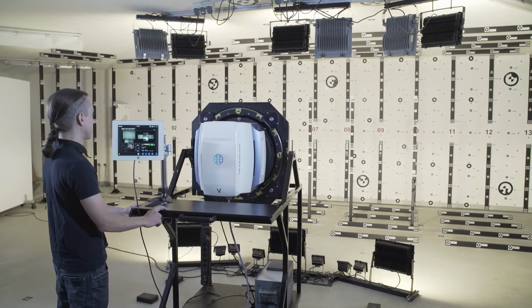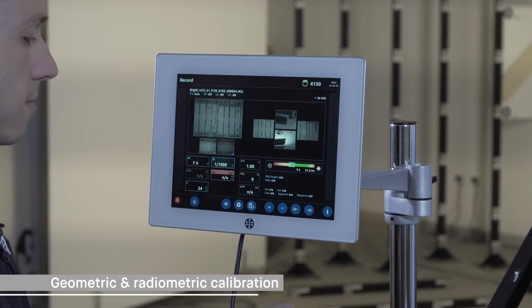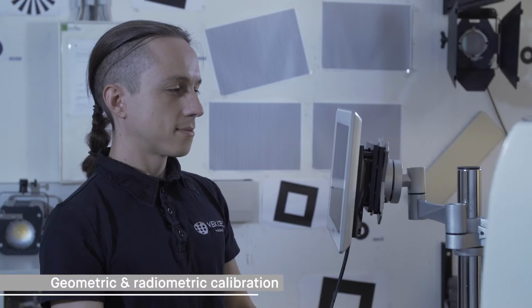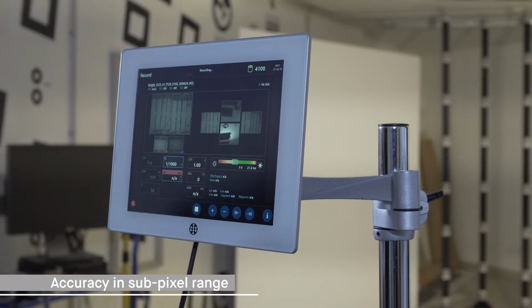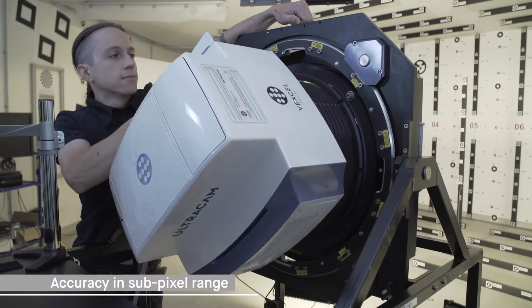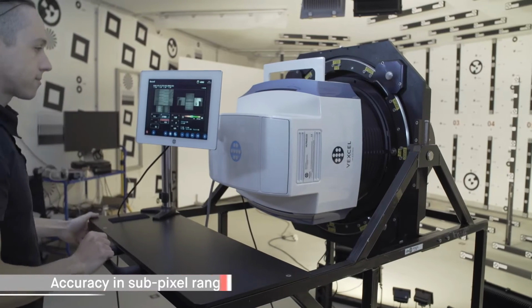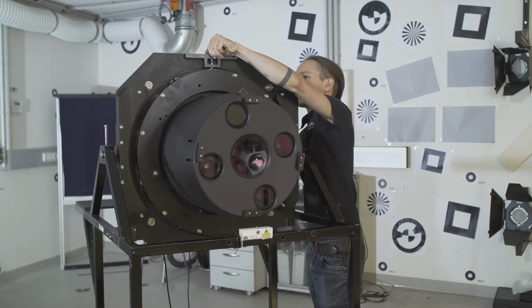The camera is fully calibrated with respect to its geometry and also with respect to its color appearance, so with respect to the radiometry. All in all, that leads to an accuracy in the sub-pixel range for the whole camera system. And with that setup, the UltraCam Osprey is fully compatible with our photogrammetric camera lineup like the UltraCam Falcon and the UltraCam Eagle.